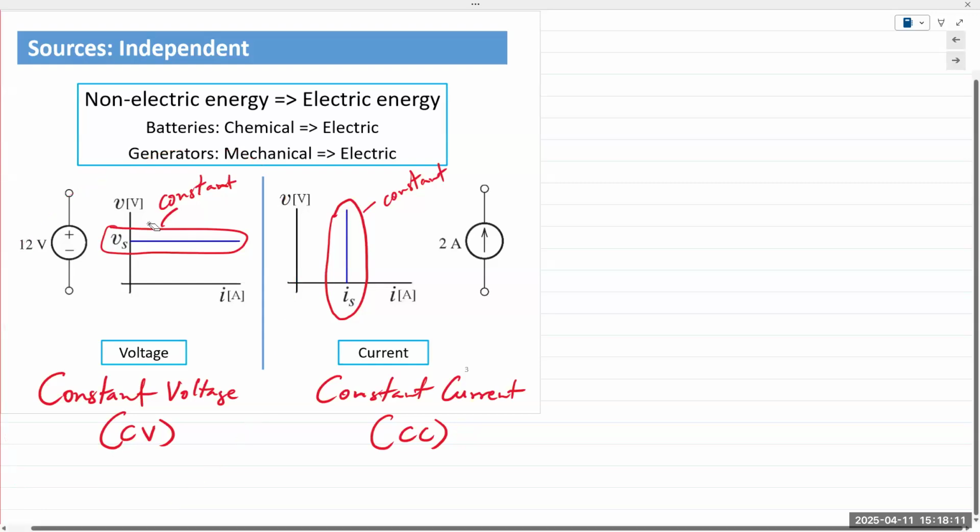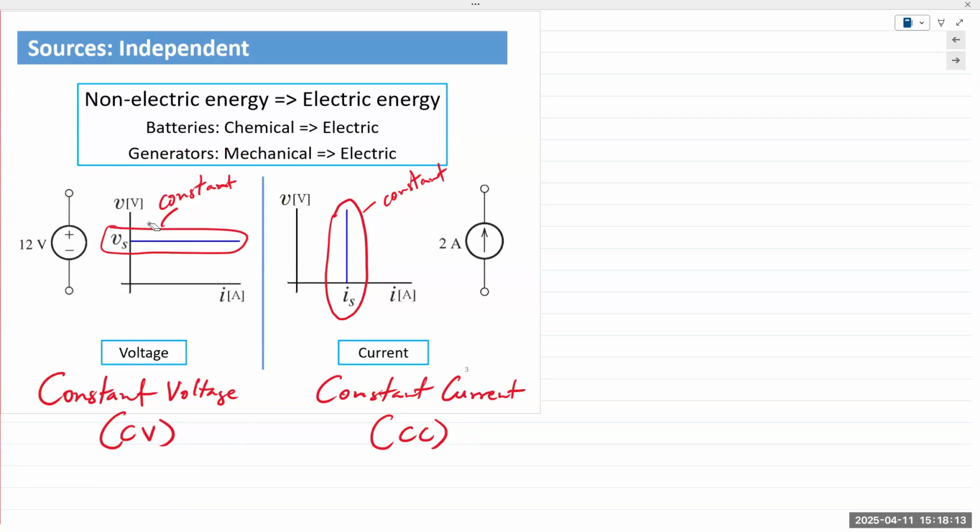Okay, so if you connect a very low resistance load in there and the voltage is high, or there's a short circuit somewhere in there, the current's going to increase by an abnormal amount. So unless you set a current limit on there, you're going to blow something out. I will come back to this after we get done with Ohm's law. But for now, does this make sense?